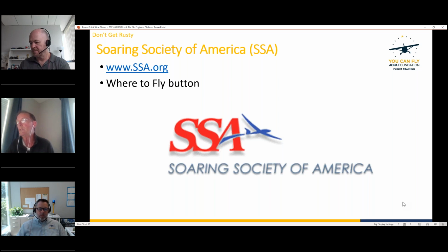So if we're in Class E airspace, it's 500 feet below, 1,000 feet above, 2,000 feet out the side is the requirement. So we can't go any closer to the cloud base legally than an airplane can. But the lift goes higher. It goes into the cloud and all the way to the top of the cloud. Although as it gets to the top of the cloud, it wouldn't be enough to actually support a glider.